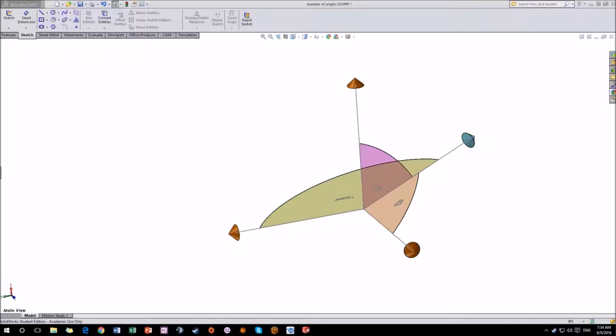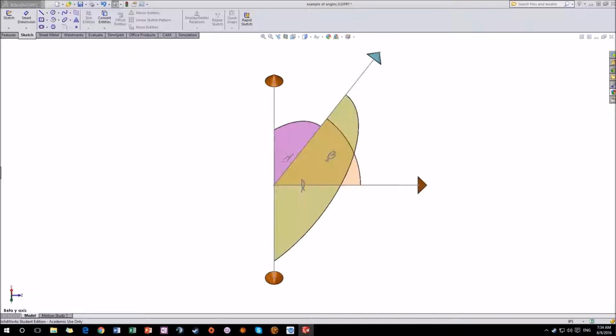I'm going to go out of order and start with the y component of force 1. For this, we will need to look at the plane that is created between the force and the y-axis, which will be like this. And then I'll disable the other angles to help us see the beta more clearly. Now when we look at the force this way, it doesn't look as complicated.